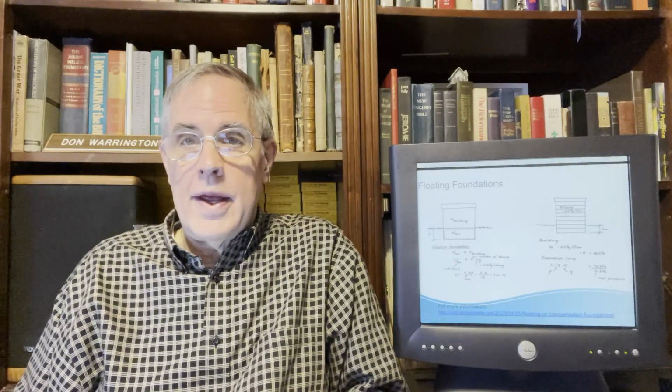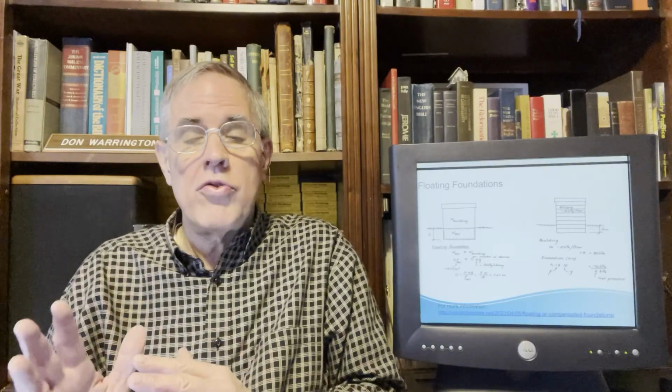In the case of soils, however, soils are intermediates. In fact, Verruijt points out that we can consider very, very soft clays almost like a fluid, and we can also assume that their Poisson's ratio is a half, which is basically what a fluid has for Poisson's ratio. But really it's kind of a gray area. Most floating foundations are done on relatively soft soils, where the soil is approaching, but not necessarily hits, the fluid.